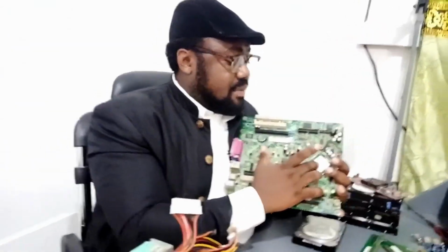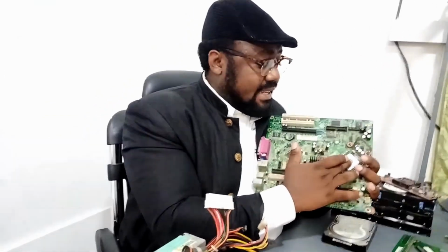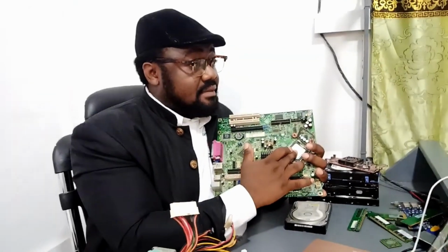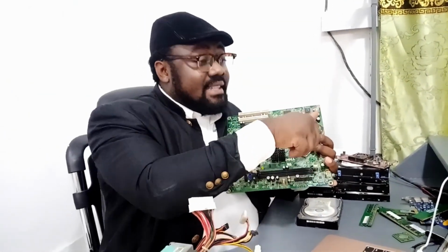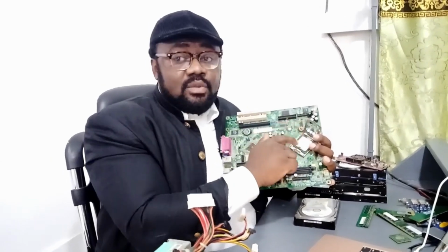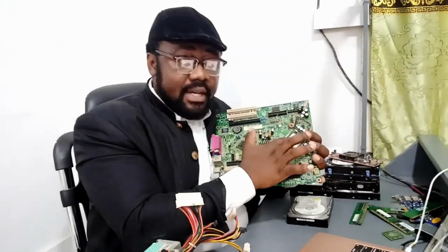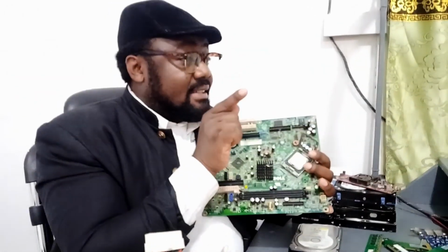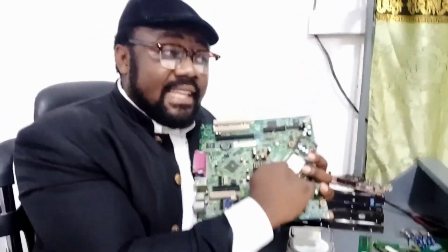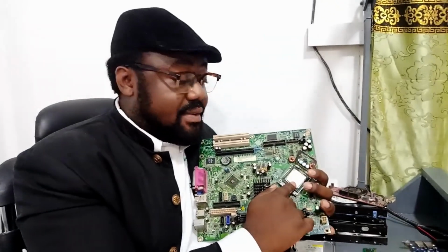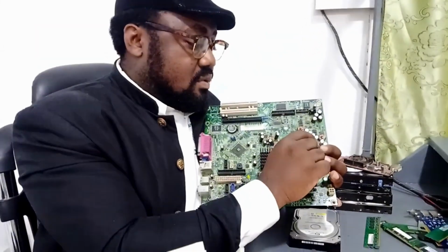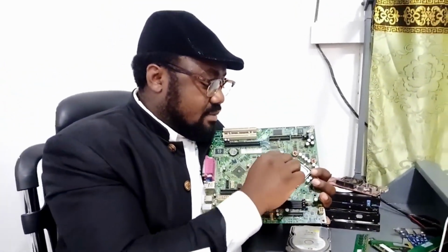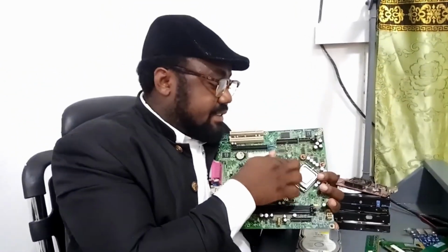Remember, the CPU needs to be connected in a very specific way. You can't turn it the wrong way, and to be able to fix the CPU well, you need to study the shape of the CPU, because there will be an indication that tells you how to place it in the CPU socket. Please, are you with me? Okay, so usually the socket needs to be locked, so we lock it here.